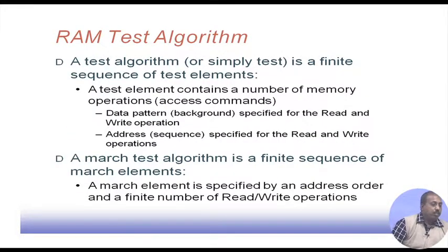A test algorithm, or simply a test, is a finite sequence of test elements. A test element contains a number of memory operations. So, what is a memory operation? We may like to read the content of the memory cell, or write some value onto the memory cell, maybe write some value and then after some time try to check the content, to see whether the operation was successful or not.